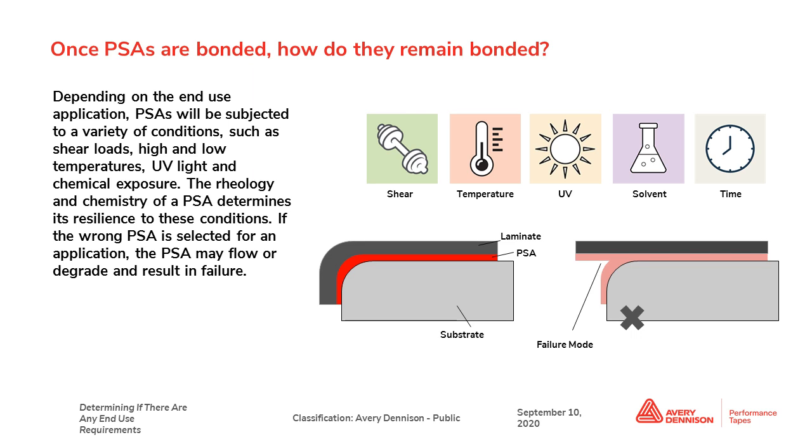So an example I like to give there for UV light is if you had a window film bonded to a window and you're using say a rubber adhesive. Rubber adhesives are not known for great UV light resistance. And actually what begins to happen is they start to brown and degrade, and they lose their viscoelastic nature, and then they could ultimately fail.